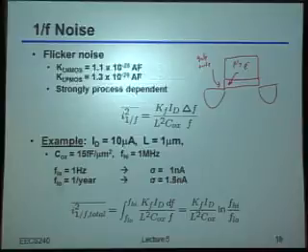Okay? Because all it does is it says, well, now I need one less electron on the other side to essentially have the same equivalent voltage applied, okay? Or one less hole for that matter, okay? So if you change the threshold voltage of a MOSFET, of course you change the drain current density for a fixed gate-to-source bias, right? That therefore means that this process of electrons hopping into these traps and out of the traps can cause noise, not thermal noise, at the output of the device in terms of a drain current.